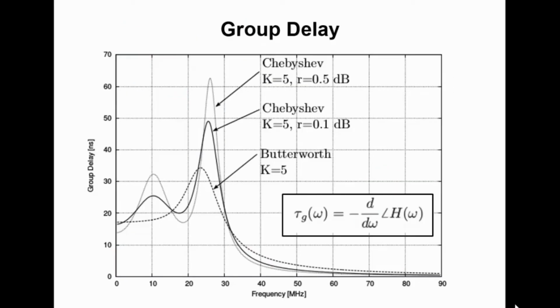The way we normally characterize this dispersion is through a parameter known as group delay, or group delay variation. And the group delay is simply the derivative of the phase response with respect to frequency, which is just a measurement of the delay, as I just pointed out. So we can actually plot that delay. Again, this is simply the slope of the phase response. And the nominal group delay variation, of course, is perfectly flat. That would mean there's no dispersion. This filter could have no deleterious effect on modulations, which are phase sensitive.